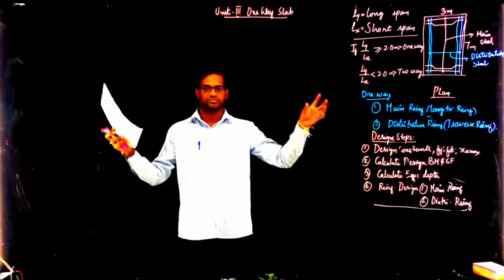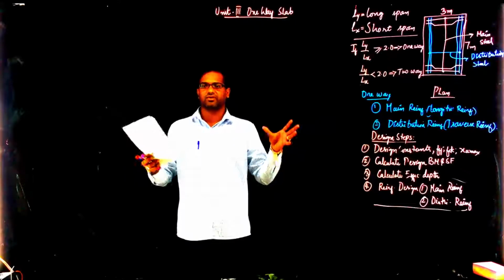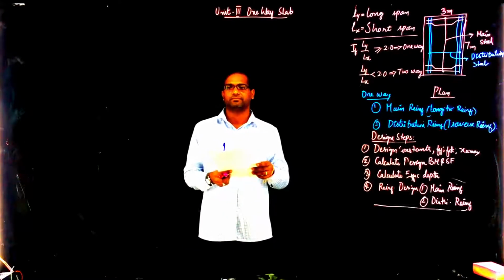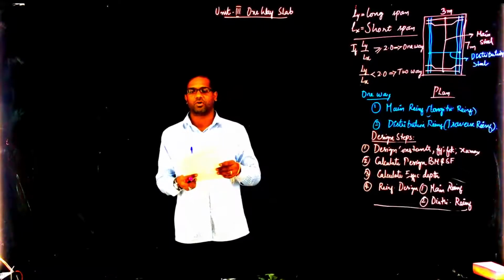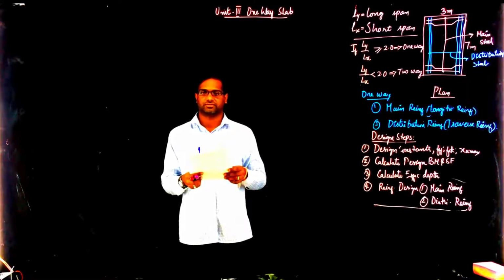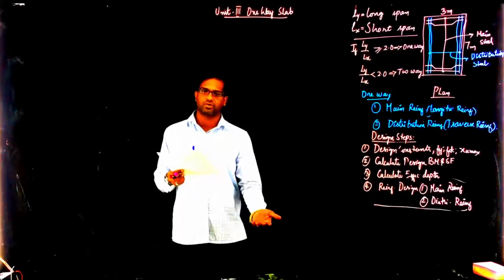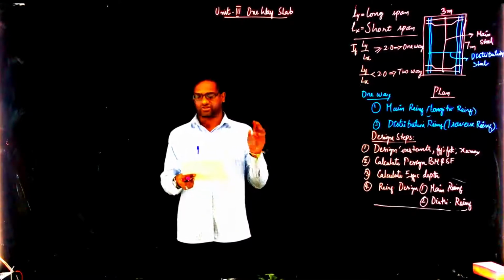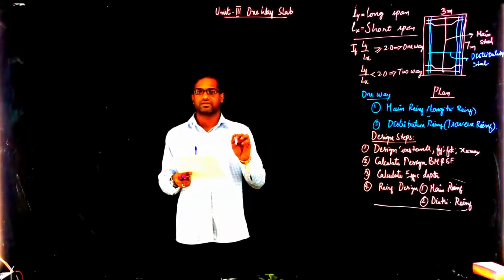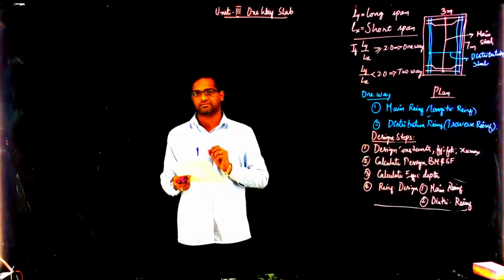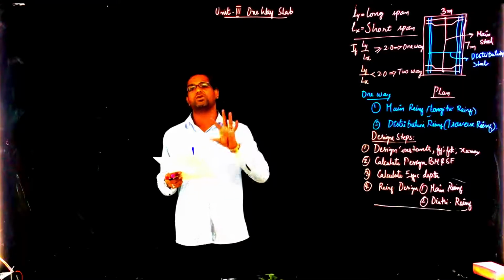Wall thickness: the slab is provided on this wall. Wall thickness is 300 mm. Lime concrete finish, which means over the slab they have finished with lime concrete, 75 mm thickness. You have to consider that also in the design part.